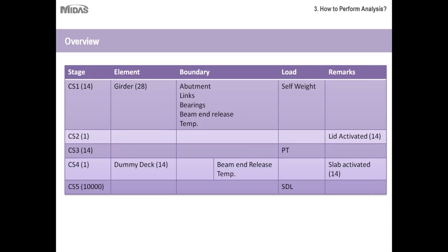So therefore you can see the load there. I have not modeled the weight of wet concrete on the structure. I agree this is important. So you can consider the weight of wet concrete applied in this stage. And in the following stage, we have activated the members that represent the deck on top of the girders. And it is at this stage we'll remove the temporary supports in the beam and releases that were there to simulate the splice connection and the shoring members.